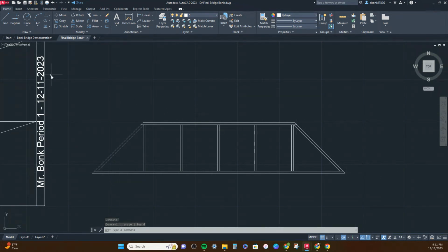And then simply finish this up by drawing diagonals. What we're going to do is, here, this should be a V shape from the middle out, to be done engineering-wise correctly here. Watch this. I'm going to draw just, this doesn't have to be a double line here. But what it should be, if you're doing it properly, see I'm striking the L on the keyboard. It brings us up. You just hit L and enter, if you prefer not moving your mouse up and clicking the L button. Hit the escape key to finish that. L, enter. So I'm starting this line.